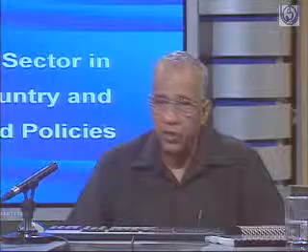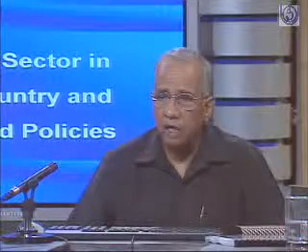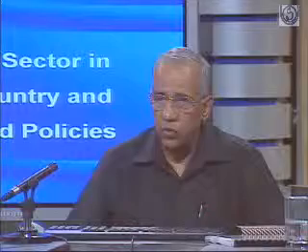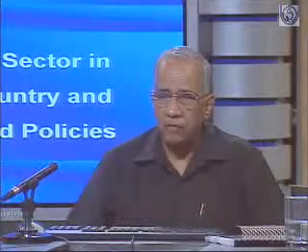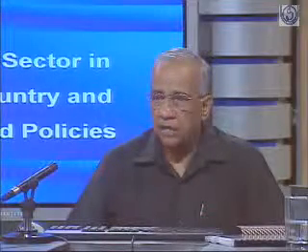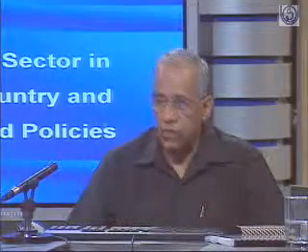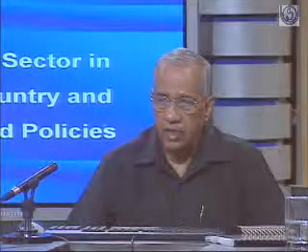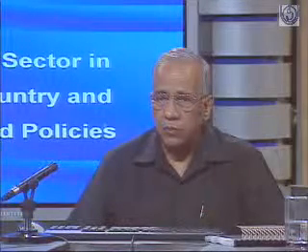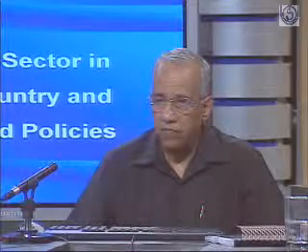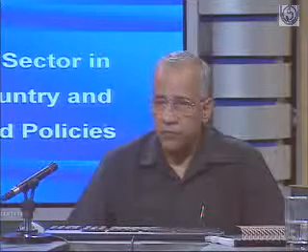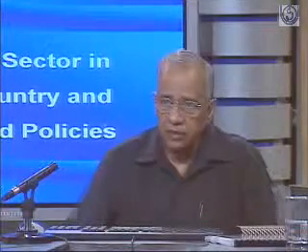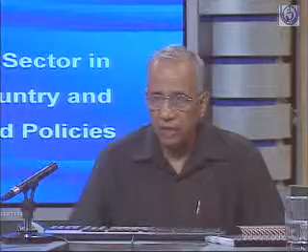It becomes uneconomical, and therefore the generator would not like to generate lower than 70% generation. If by any chance you force him to generate, next time he will prefer to keep his unit shut down, because it is very uneconomical for him to raise the generation from below 60% to the full load generation. This is one limitation. Therefore, on such occasions, hydropower comes very handy. With hydropower, you can quickly load the machine to full load.